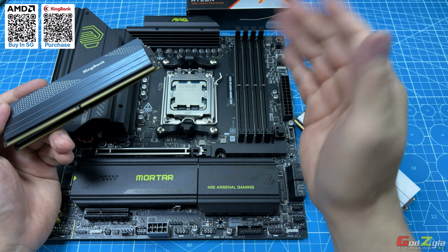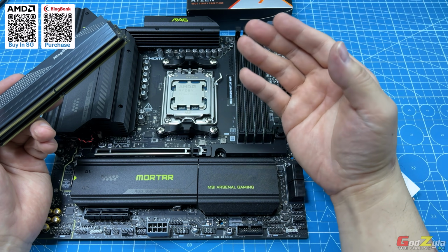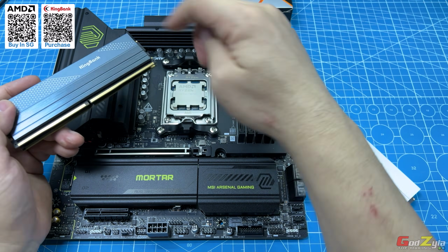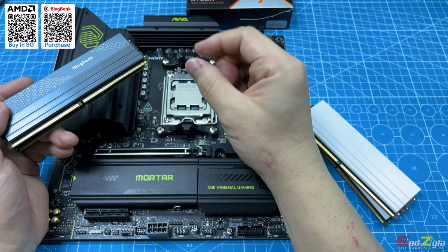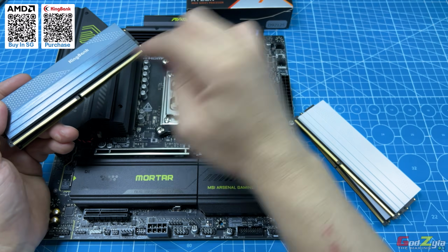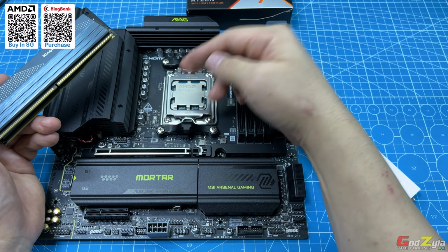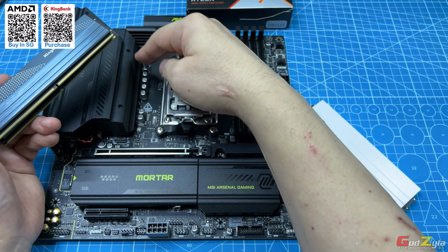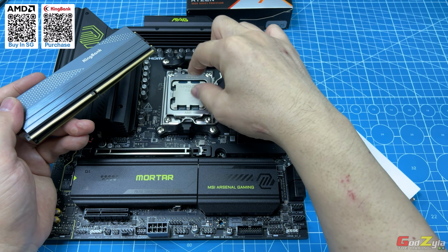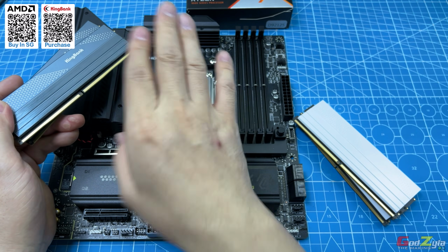Even I checked with the AMD personnel. Now, why is it that you should not run more than 1.2 volt? The communication between the processor and the RAMs, there is a chip which is the IMC, whereas here is the PMIC, if I'm not wrong. They communicate with each other, and on your power phase on the motherboard itself, where you have 12 plus 2 plus 1, 12 is in fact the processor, 2 is in fact the SoC of your processor and the communication to your RAMs. So that is the voltage that you need to take note of.